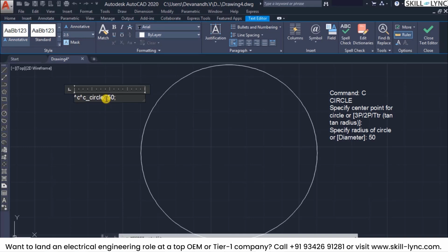To quickly look at them, we use the semicolon for enter, and if there is a requirement for a blank space, you can enter it by typing in space. The slash is for the user input, and the underscore is for translating AutoCAD commands and options that follow it to the English language. Then you have the hyphen, which will run the command line version of a command. That is, if the command line version is going to be C, then you can replace it by hyphen C.